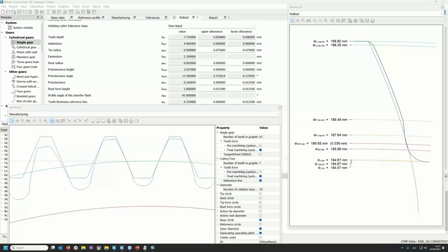Are there any alarm messages on design? Example, short leading of a hob by too many degrees, or if we use a non-manufacturable tolerance of hob features, too high to make the cutter. We have added several checks for the tolerances, if they make sense or not, for the Service Pack 2. So this will be available for the Service Pack 2.